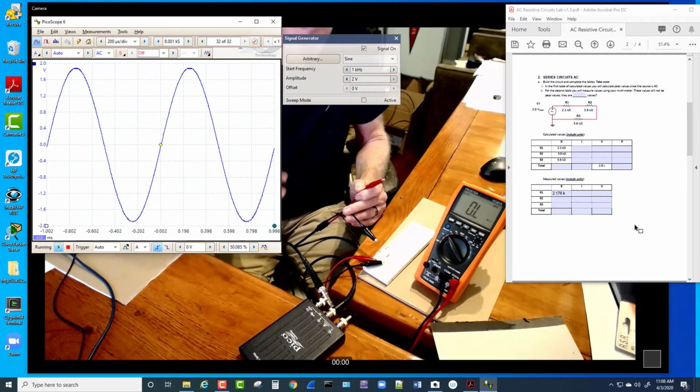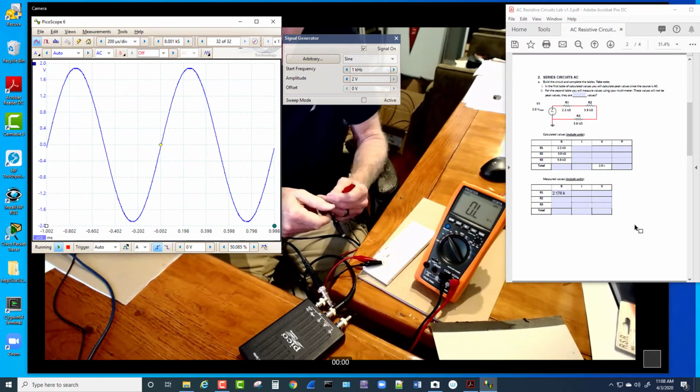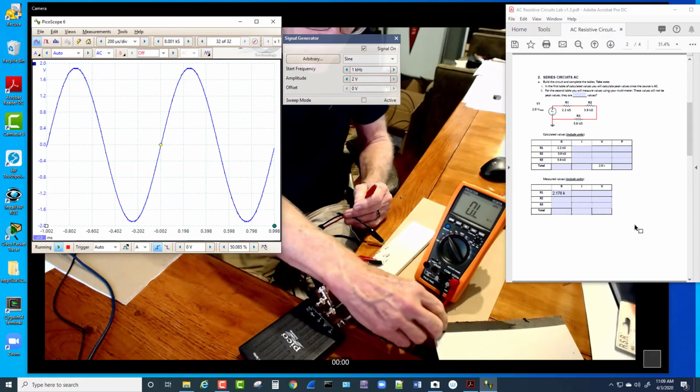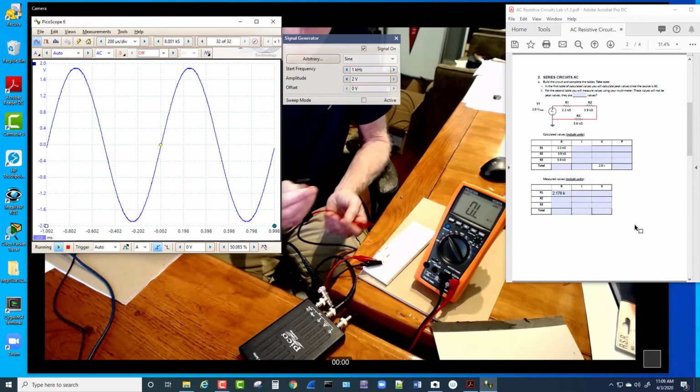This is a similar situation to what you have in commercial and residential installations where you've got 2 wires or you've got a bunch of lights or motors or some fixtures, and the temptation is, well, just go in and measure them. Now you get away with that on the multimeter because this black has no relationship to this black or that black or that black.